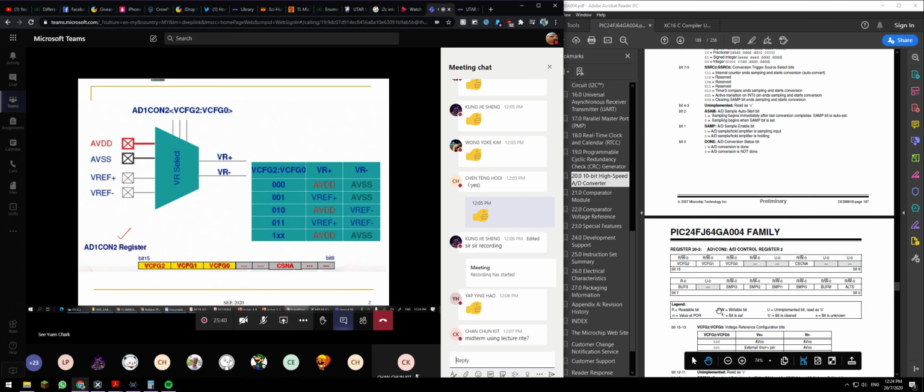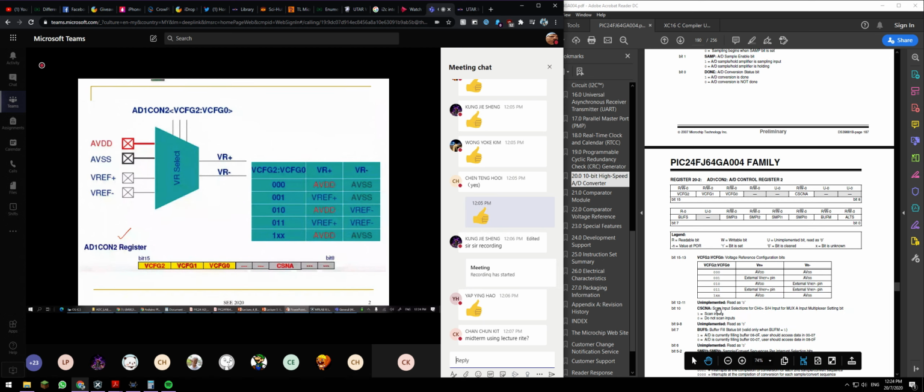For example, if I choose both internally, then it's 3.3 volts and 0 volts. Or, for example, I just want to choose 1 volt, so I utilize one of the ports, and the other is ground, 0. That's perfectly all right. In this case, we just sacrifice one input output port. Again, it depends on your sensor. Is it needed to have such high accuracy?